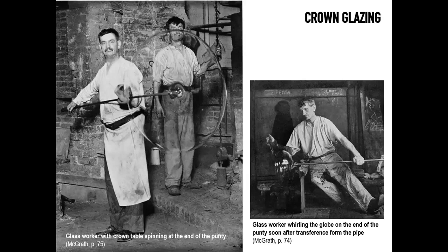And you can see, however, how in the middle of a crown glass there is this bullseye, which is going to stay there forever, and it will have to be somehow eliminated, as we will see. And you can see here another stage of the process before the glass is reduced into this beautiful, very crystalline disc, where the glazier is working at an intermediate stage between a spherical lump that was extracted from the furnace and something more of a bell-shaped profile, and he's helping himself here with some tools to ensure, whilst the glass is still spun, there's a certain consistency of shape that can eventually lead to this flattened cylinder.